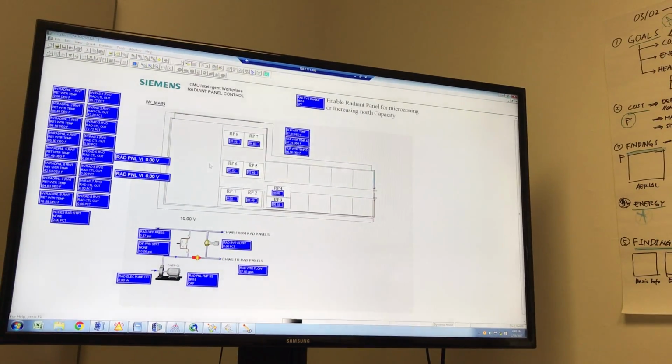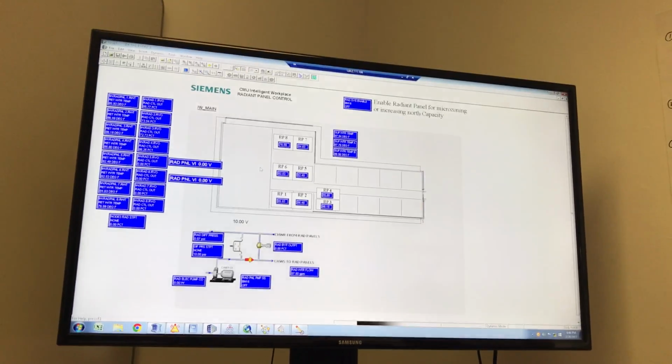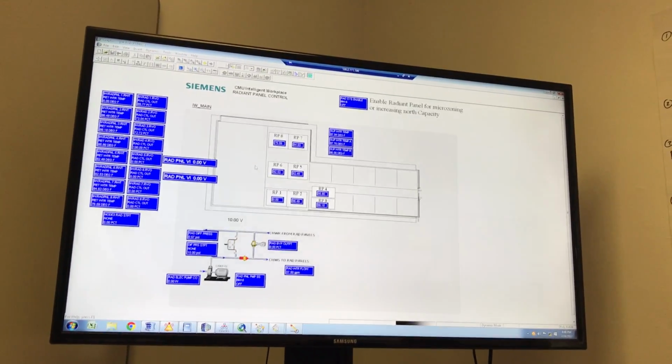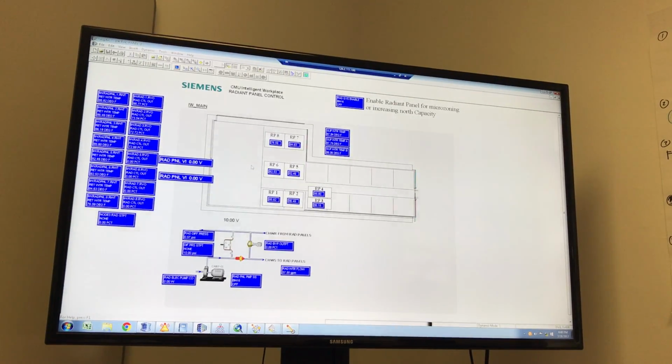If it's cold, if she's around set point or below set point, her radiant panel will be on automatically. If she's above set point, it will turn off. I see. So what you did was you overrode those rules, so it's not as if those radiant panels actually come on if the temperature drops in those spaces. That means they have an additional level of thermal comfort than all the rest of us in the office. That's right. Okay, I get it.